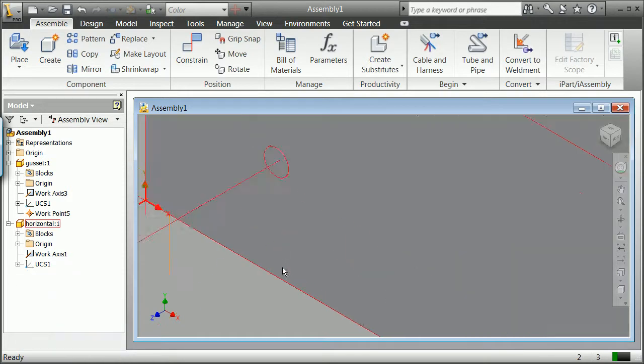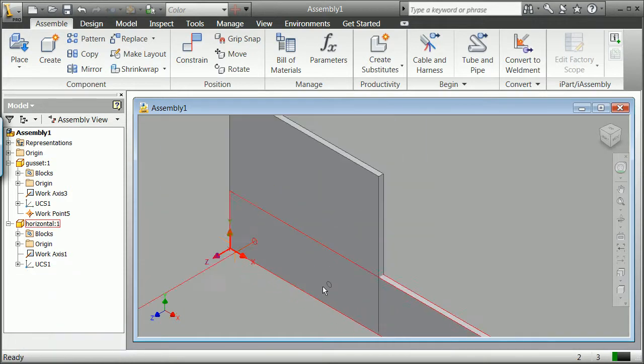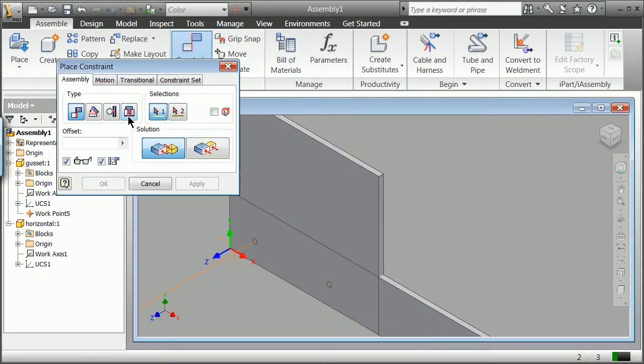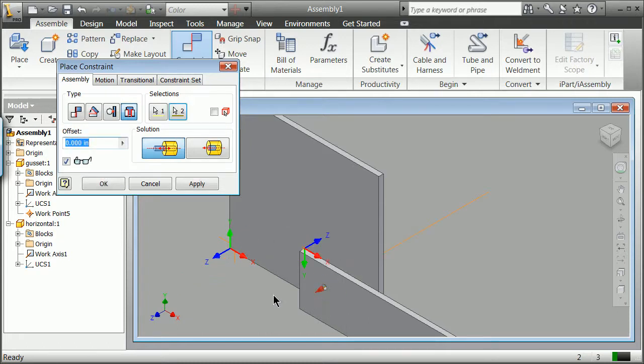I don't know that you can necessarily delete, but one thing that you might do instead of doing things by matching UCSs is learn one of the more important ones, I believe, when you do a lot of stuff, is this kind of insert. And that insert, generally, if you kind of grab two holes, very typically things are going to line up pretty nicely. And you notice right here this offset. I'm going to go ahead and just leave that offset at 0.